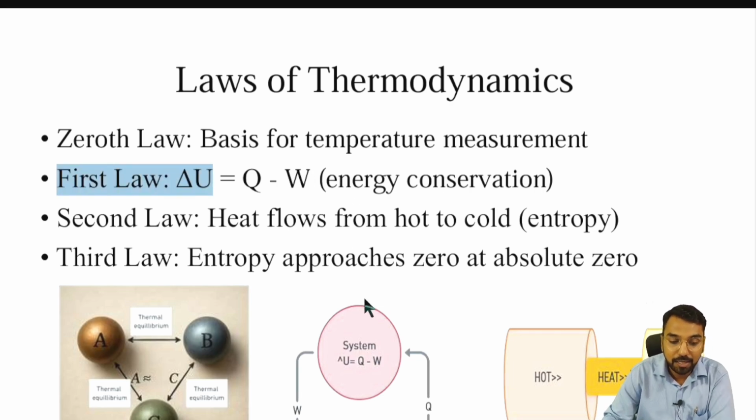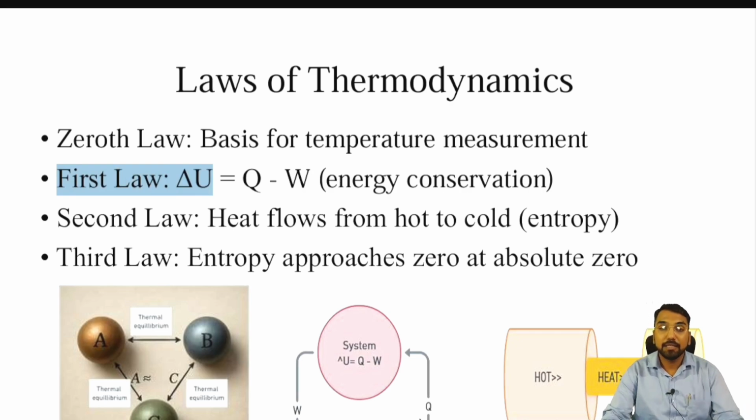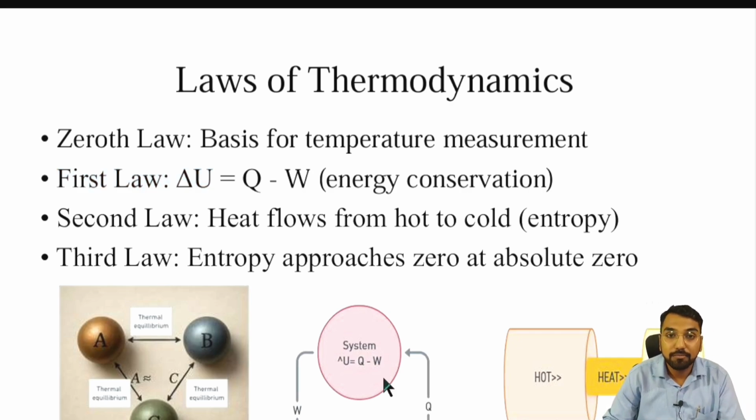That is energy conservation. What is meant by energy conservation? As per the statement, you have known that energy can't be created. Energy just changes from one form to another form. So, by seeing this figure, if I put heat Q into this system, and some work is delivered, that means some energy is also delivered. Then the change in internal energy is nothing but the heat minus the work done. That is why the first law of thermodynamics tells us about energy conservation.